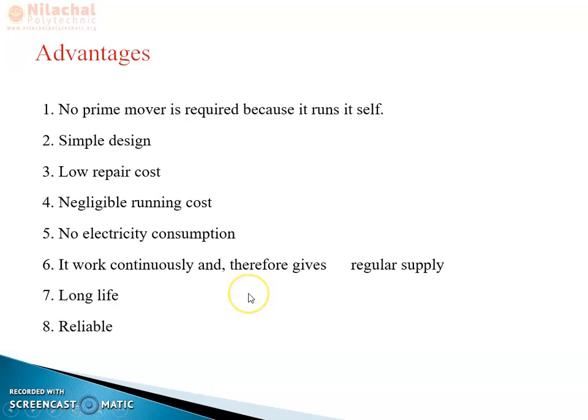Let's come to the advantages of this hydraulic ram. It is an automatic system with low maintenance, and because there is no moving part here, wear and tear is very less. That's why the running cost is also very negligible. No electricity consumption, long life and reliable.